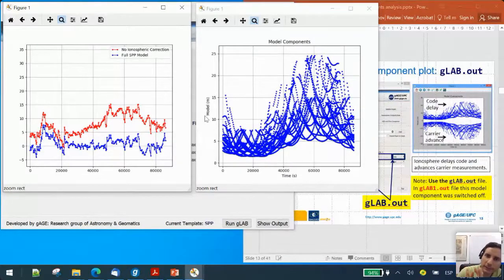With almost only positive errors, we can see, or this explains why before second 20,000 we have very little ionospheric content. This is linked because at this time we have the night. We don't have the ionization generating free electrons in the upper layer of the atmosphere, and this is why the model has a low value, up to around 1.3 meters. This is why in this first part of the day, neglecting or not neglecting the ionospheric correction does not impact so much.